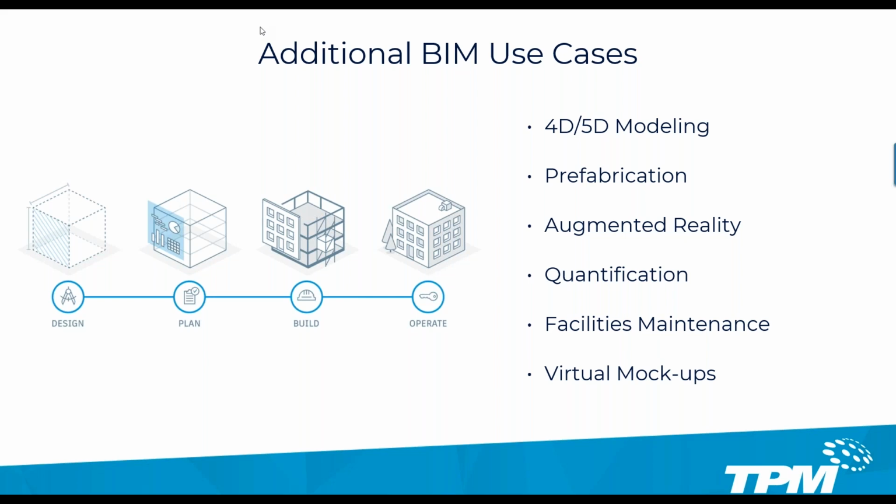I also did want to mention, I forgot as I say scan to BIM aloud, there's also the ability to do scan to mesh. It's a little bit of a cheaper alternative, and it's less accurate, but it takes that point cloud data and turns it into a solid mesh object. It's a lot lighter than model elements from Revit that have been traced over that point cloud.